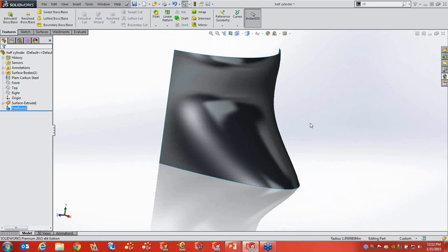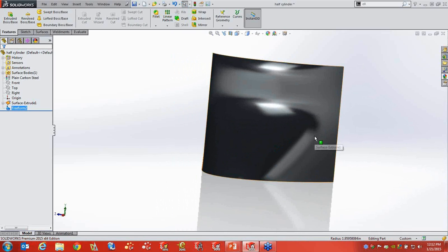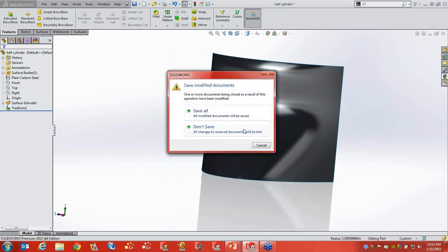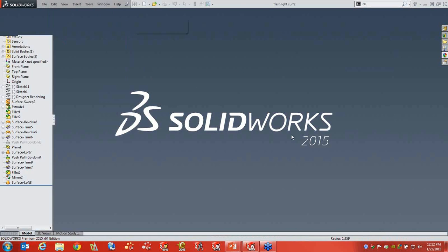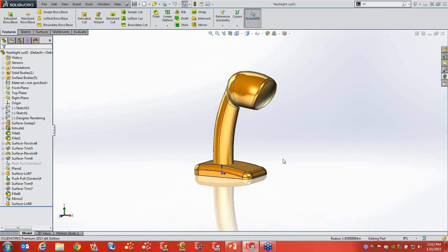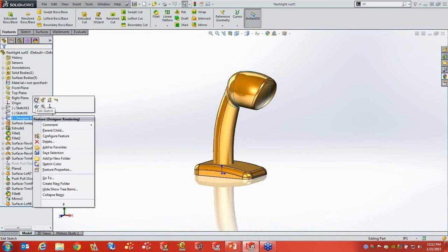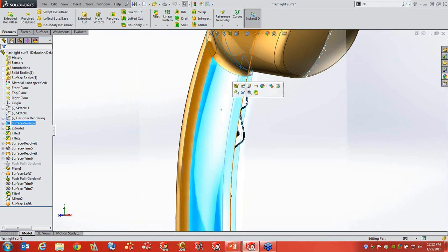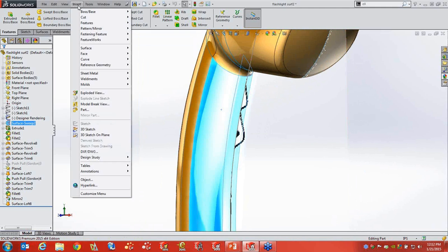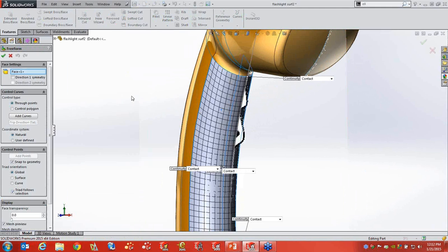Okay, so Freeform, in its very basic sense, and just a simple surface, allows you a lot of different control, but very predictable control. When you get into working on surface models, it can be helpful to utilize things like existing sketches to modify the surface to match that. Here's the same kind of technique. I want to freeform this. I want symmetry in direction 1. I want to add curves.